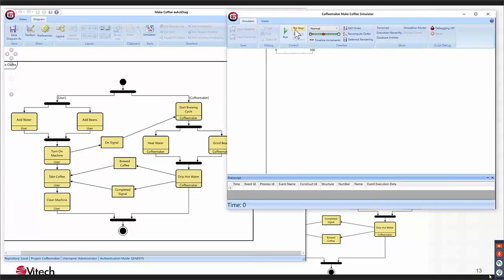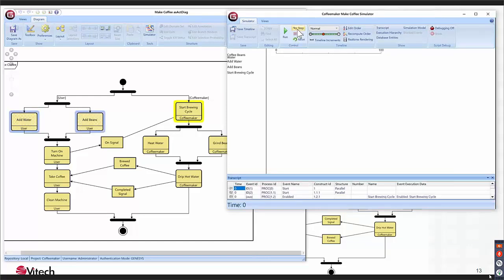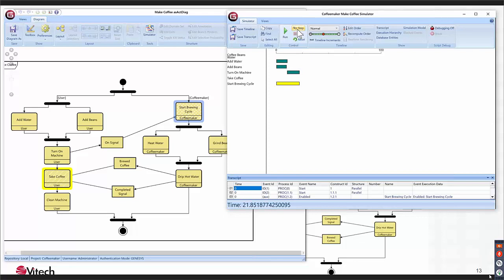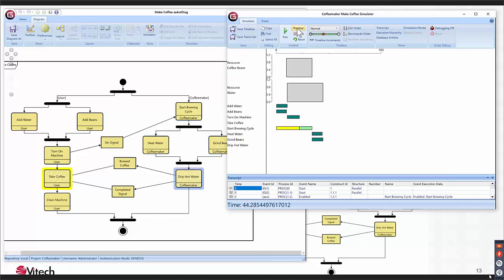Now, at the first level of dynamic verification, we're really just looking to see, does this work? When I have forking paths, I can often create deadlocks where something upstream is dependent upon an item that isn't generated until later. And so we can have processes deadlock against each other. I'm going to step through at this first level and just make sure that it all works. And the answer is, this was a very simple model. Yes, it does work.